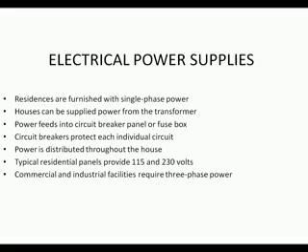Refrigeration compressors have a very high starting torque. The starting torque is the twisting force that starts the motor. At the high starting torque, the current is called locked rotor amperage, or LRA. That's the amperage that the motor is drawing as it's starting to turn. The full load amperage is the amperage when the motor is at its maximum running load. In other words, it's already started, it's running, but it has a load on it. The rated load amps is very close to the full load amps.